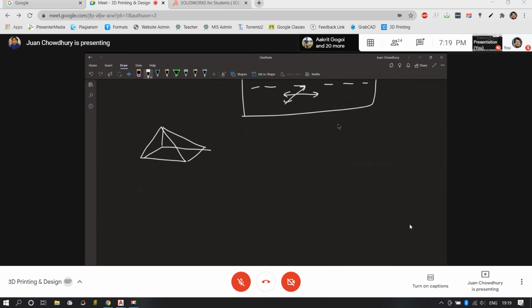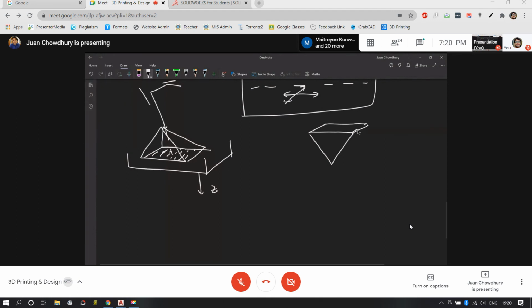The conventional technique would be you point the mirrors of the laser in such a way that printing takes place layer by layer, and the tray on which the resin is kept, you bring it down sequentially and replenish the top layer with resin. That is one way. The other way is you invert the object.